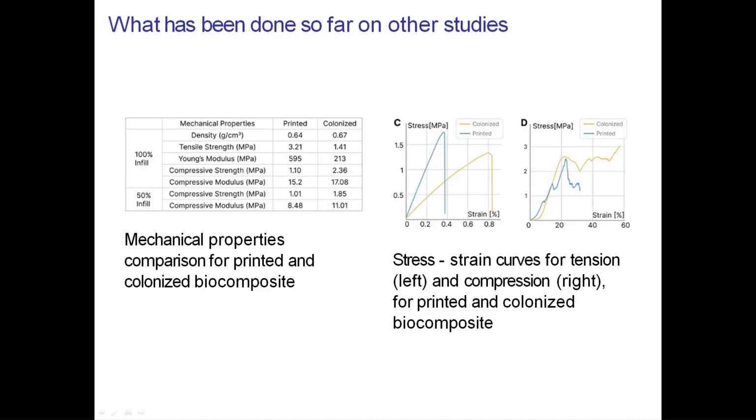Also, the authors have calculated some mechanical properties of the printed product, both before and after the colonization, as well as the stress-strain curves for tension and compression, and compared the results. We can see that after the colonization, the tensile strength and Young modulus decrease, while compressive strength and compressive modulus increase.